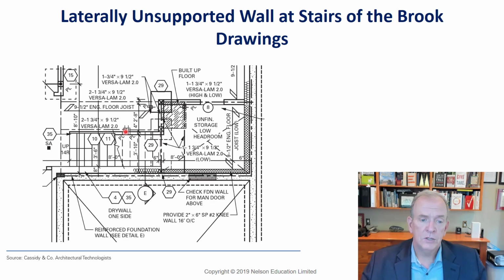And that's a good idea that you start to understand that. If you're looking at a set of construction drawings, I'd be looking where there's big window openings, where there's staircases, for rebar. Where's the rebar got to go? Because I know in my head it's laterally unsupported, so there should be some rebar going in there. A lot of times in house foundations, they're not reinforced concrete foundation walls because they're usually not going deep enough, or there's usually not enough loads, unless there's some other soil condition that requires that, like an engineered pad that you're building on. So you're always looking for where you might have to place rebar and making sure that you put it in, because it could be missed, and that would not be a good thing for your foundation.